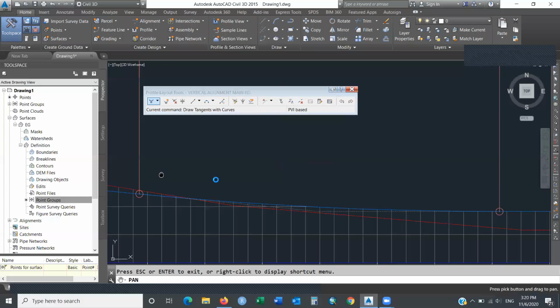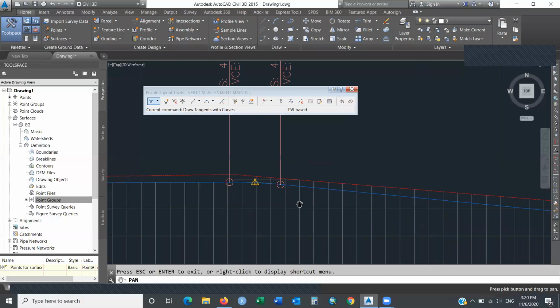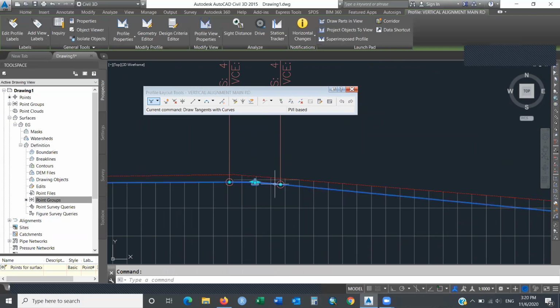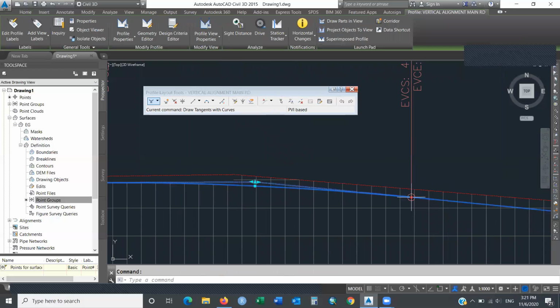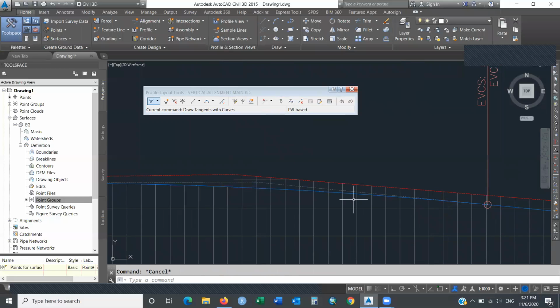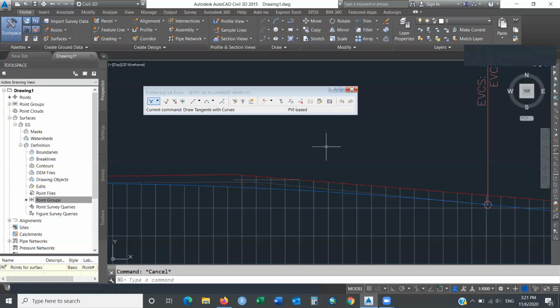Okay, so if you guys finish, you will notice that I'm adjusting my curves a little bit here and there. You don't really have to do that unless you have a question mark like this, in which case your curve side distance probably has a violation and you need to have a longer length of curve. So that will probably fix your issues. You can also go to the table to adjust if you want. So you can adjust here in this table. Okay.